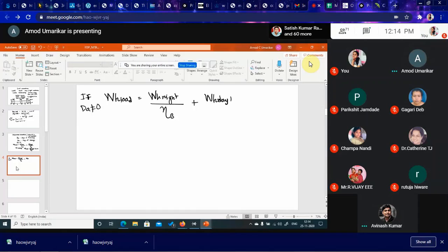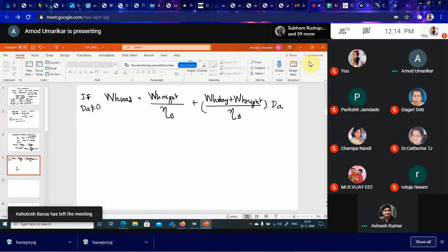WH day plus WH night for autonomous days, correct? Okay. So this it has to supply. WH night it has to supply, plus it has to supply for 24 hours, which means multiplying by the number of days. Okay, so this has to be there.